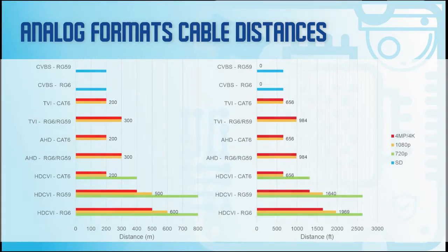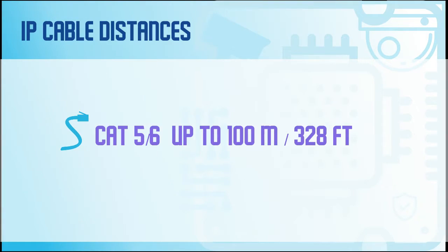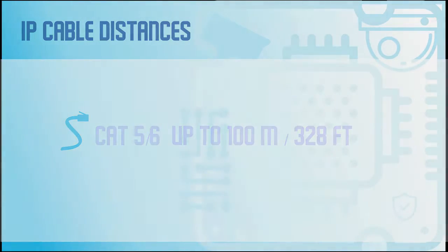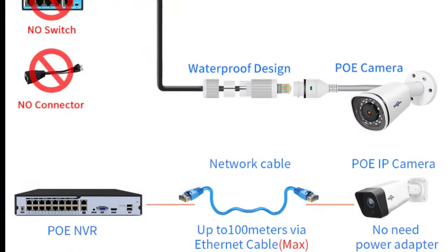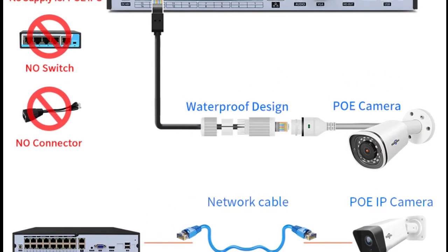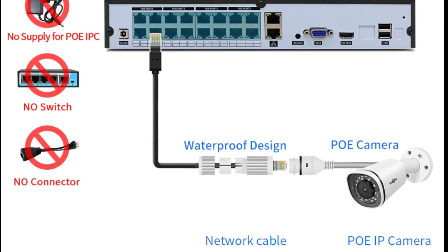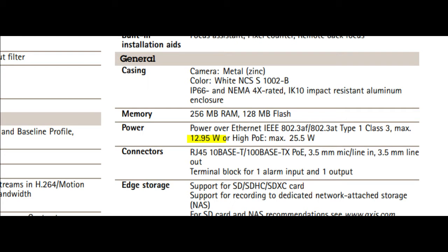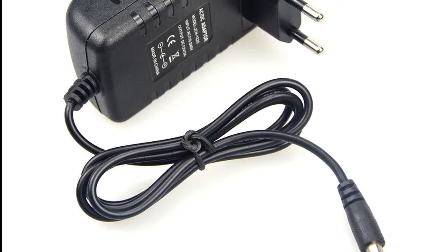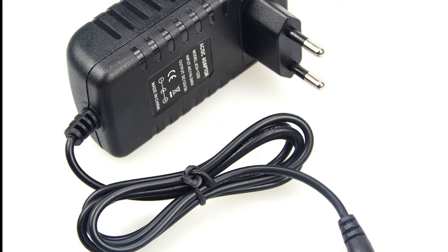Please check the cable's max distance for each technology. If you are powering the camera via PoE, always check that the power source PoE classification matches the camera spec and that the cable length is not exceeding the specs. For cameras powered locally via auxiliary power supply, check if the power supply meets the camera specs.